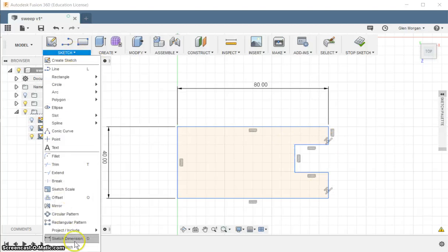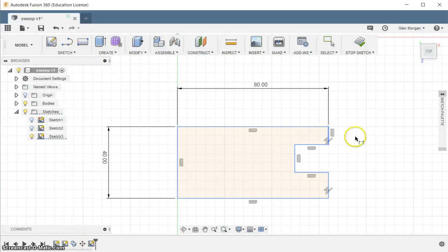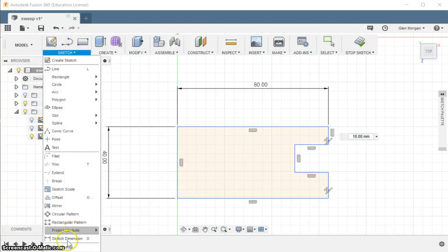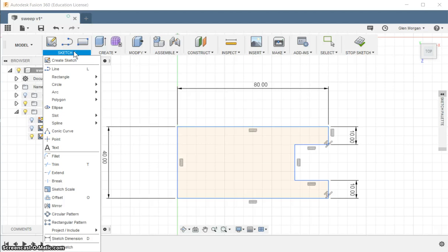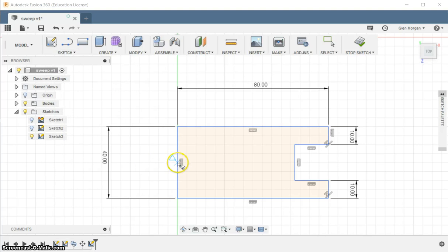And if we put some dimensions on here now, you notice at the other end we've got the 40 millimeters, so probably here we want to do 10 and 10 to keep that balanced. We might make a little bit more of a complex shape at the other end. We might draw a circle. Let's start with the circle there in the middle. We'll then trim that out.